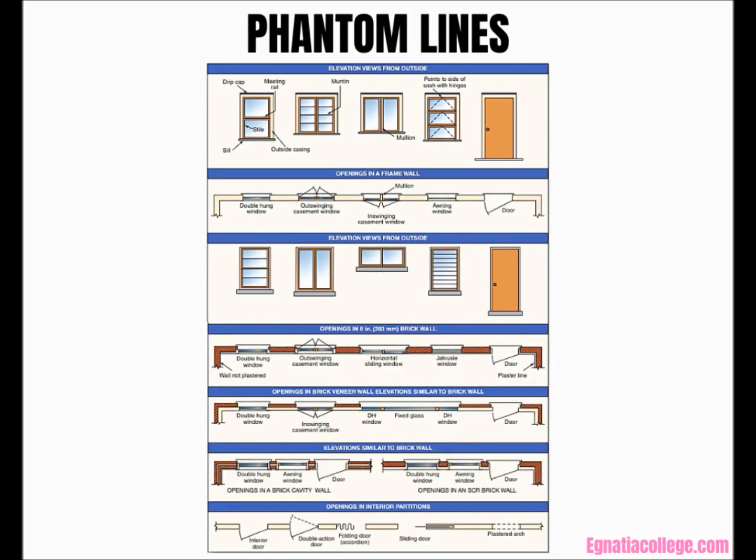Phantom lines. Phantom lines are short dashed lines, about 1.5 times as long as the dashes for hidden lines, that show an alternative position. This figure shows a double-action door where actual positions are depicted with solid lines and alternate positions are dotted lines. Closed switch positions are shown by solid line, while alternate positions are shown with a phantom line.